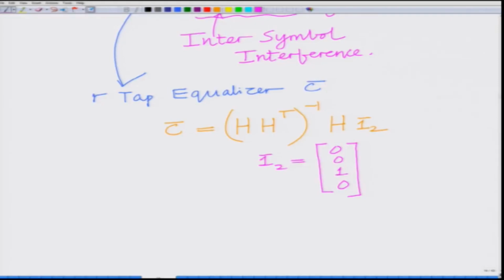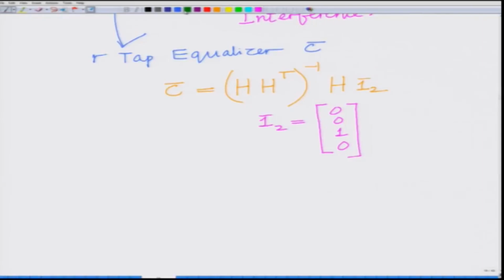derived employing the least squares principle, and then the equalizer itself is implemented as C bar transpose y bar, alright. So equalizer is implemented as C bar transpose y bar, and for this we want to find the approximation error, that is how close is this to the vector 1 bar 2. Therefore, we want to find the approximation error. Remember, this is what we have started computing.